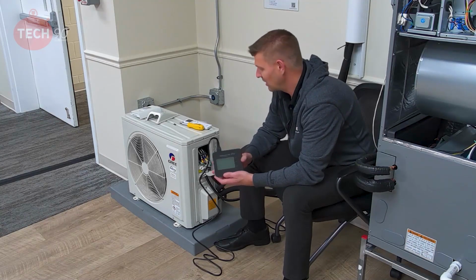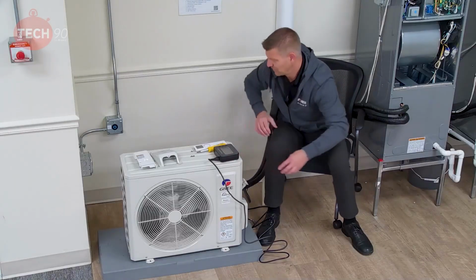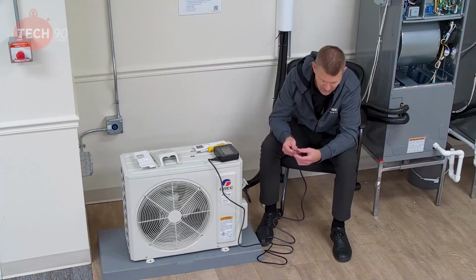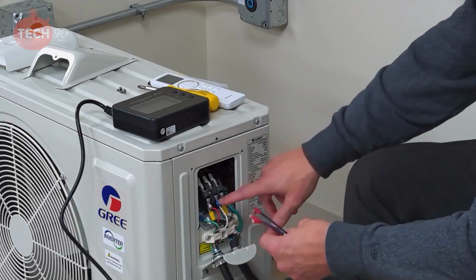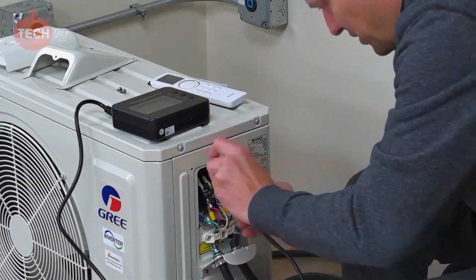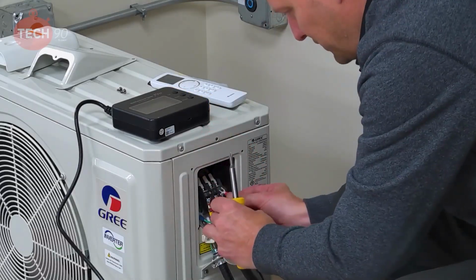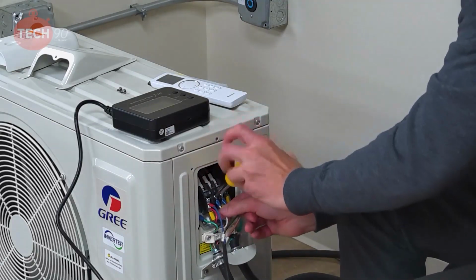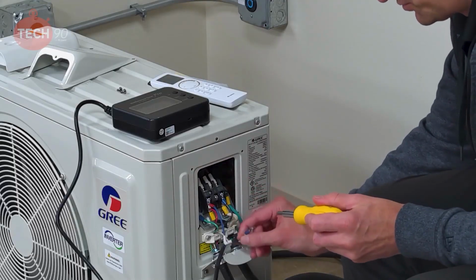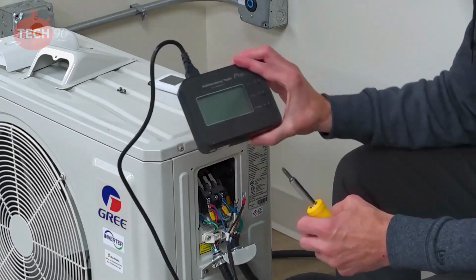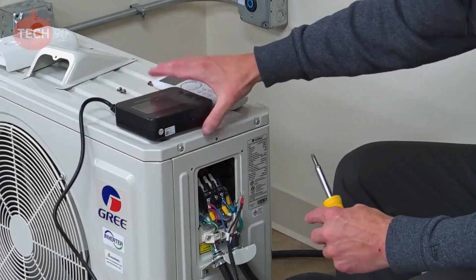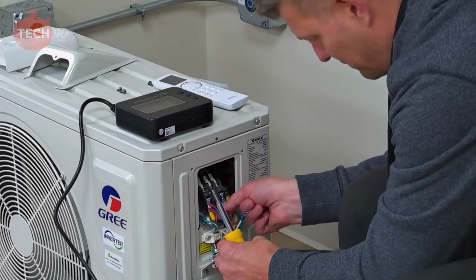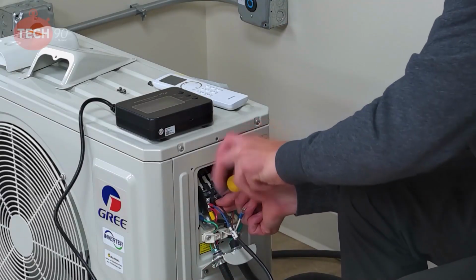So let's go ahead and wire this in. The power is off. We have 3 wires here. They are labeled for you 1, 2, and 3, just like your connections are labeled 1, 2, and 3. Hooking up 1 to 1, 2 to 2. And when we do this, we're going to disconnect number 2 that goes to the indoor head, because we're using this tool to simulate the indoor head. So that's why we're disconnecting number 2 coming from the indoor head, and disconnecting number 2 from the service tool. And we're powering the indoor head still.